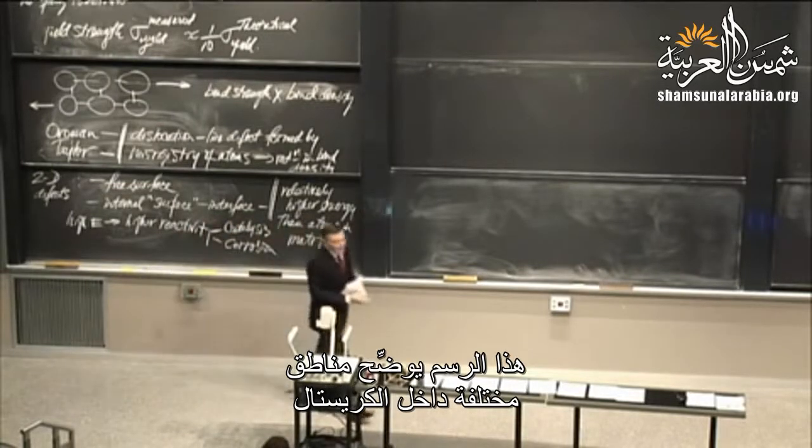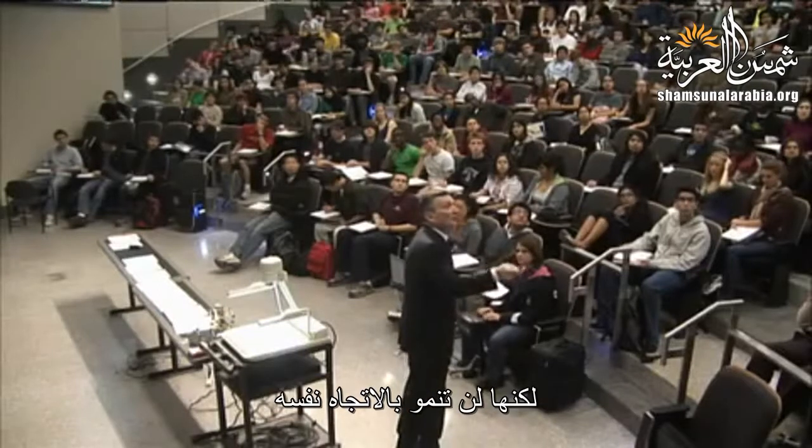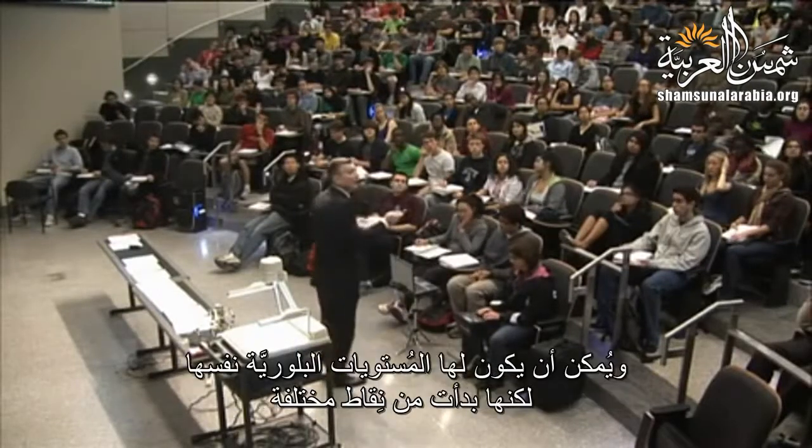So here's a cartoon that shows different regions within the crystal. Professor Dimkovich showed you on Friday the atom mix, but here we see atoms. This is simple cubic, this is simple cubic, this is simple cubic. But when they meet, they don't line up, because this formed from solidification from the melt. There might have been a seed here, and it grows outward, a seed here, and it grows outward, a seed here, and it grows outward. And when they grow outward, they impinge, but they're not all growing with the same orientation. You already know what the planes are. They could even be the same plane, but they're starting from a different point. And so there's this misregistry here. But it's not a misregistry like the dislocation. It's a two-dimensional misregistry. Actually, let's cut to the document camera. Dave, could we do that, please?